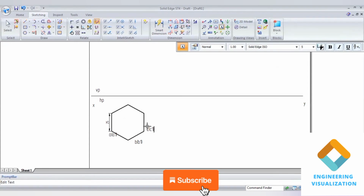Here we need to find the center of the hexagonal prism. For that, at least 1 or 2 lines need to be drawn, because since it is a prism, to find the center of the axis there is no need to draw all the lines. Inside this hexagon we should draw thin lines, not thick lines. 1 or 2 lines is enough.